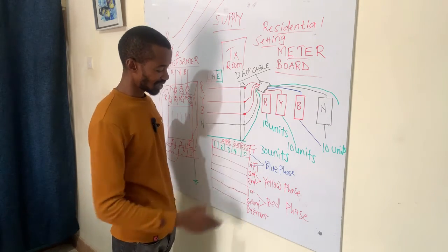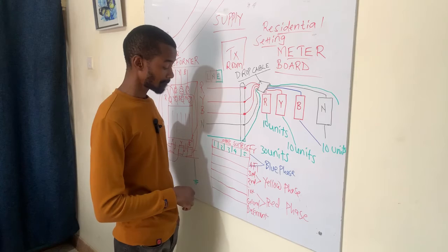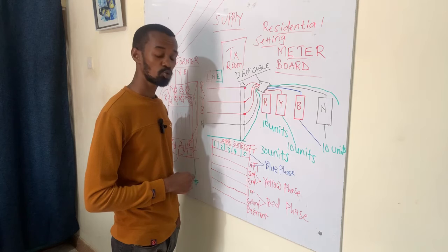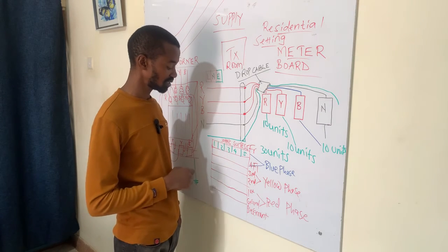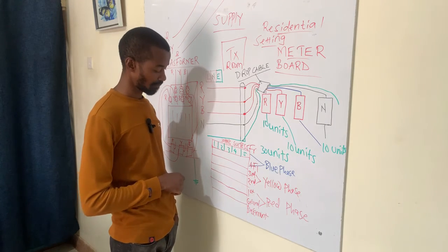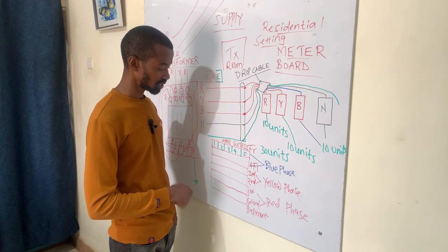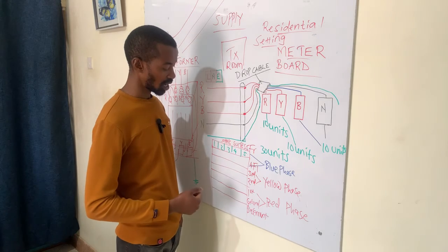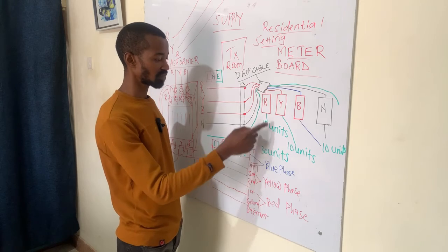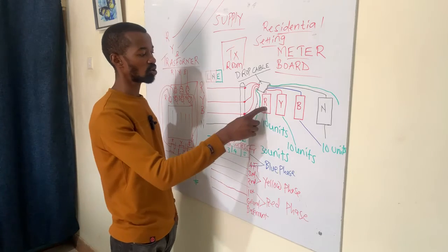So we have floors running all the way to 5 floors, or the 5th floor. Each floor, we have said, has 5 units, each of 2 bedrooms. These are 2-bedroom units. There's a guy here by the name John who has invested really well, a real estate investor. So each floor has 5 two-bedroom units, and we have said that we are going to balance. All of the units now add up to 30 units. We have simply divided by 3 to get 10 units per phase so that we do not overload a specific phase.